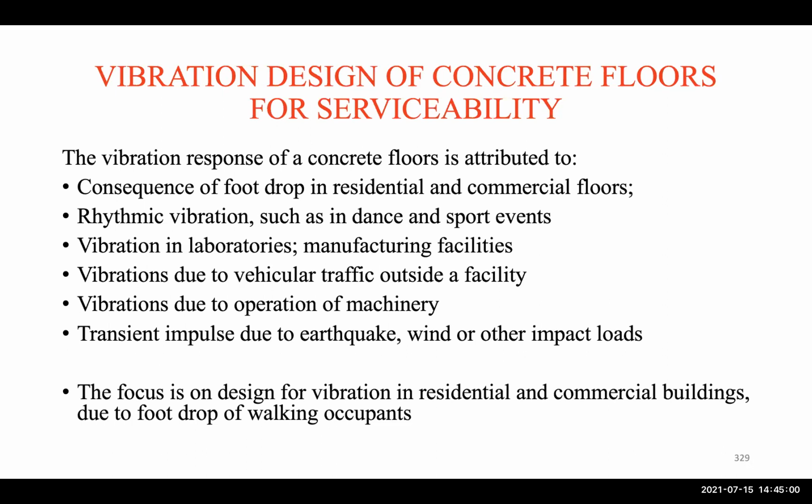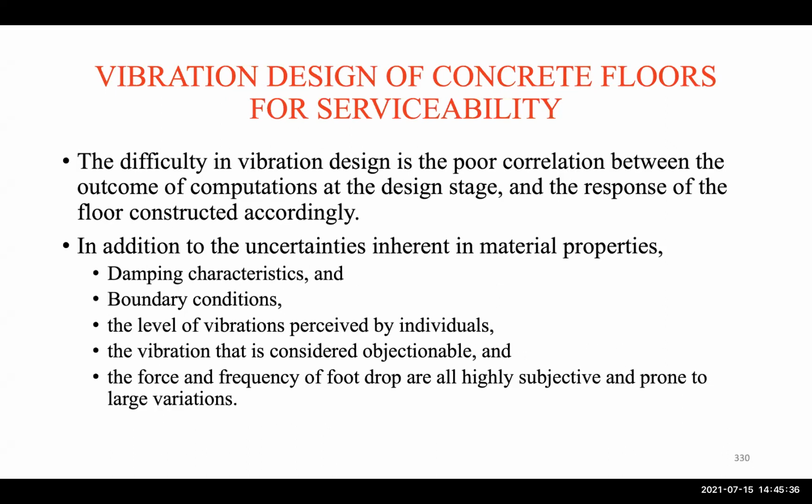So the main focus here will be on the very common application, which is commercial or residential buildings, which is basically the foot drop of a walking occupant. If we have to do something for rhythmic or manufacturing vibration, etc., sometimes you have to use more advanced techniques of analyzing concrete floors, which are available. So the analysis is not really difficult, but the criteria is different. So you have to look at the criteria for each of these categories.